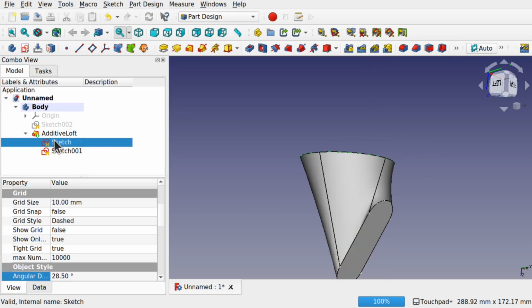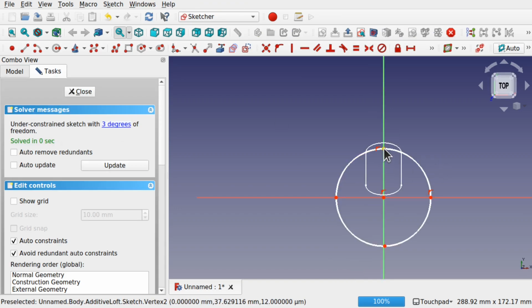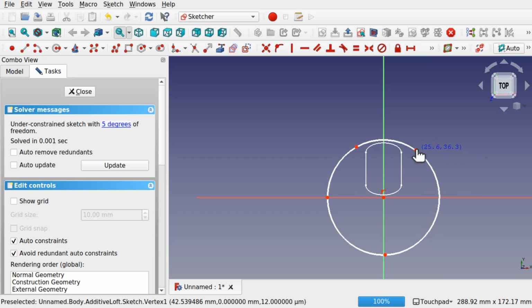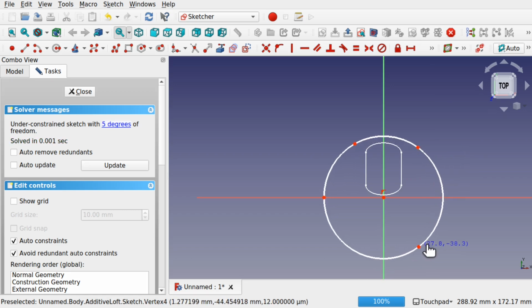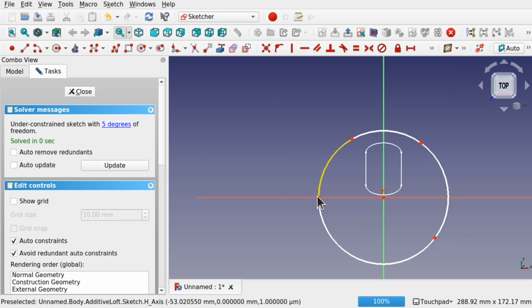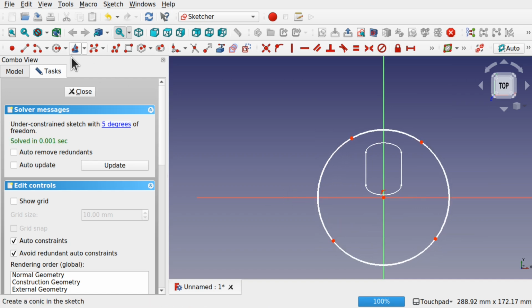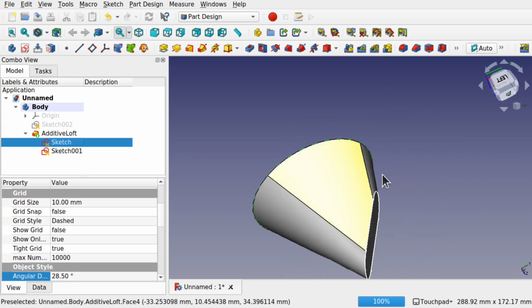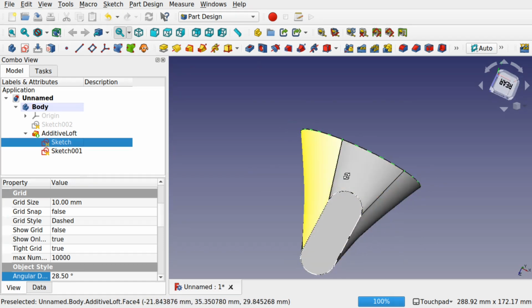let's come into our sketch and we can start looking. Let's get rid of that point on line constraint and looking at the sketch behind, which is the slot sketch, we can see that we need this point over here a bit. Let's get rid of this point on line constraint and this one up here and this one kind of over here and this one kind of this way. Hit close and then we've got better matching surface. There's no twisting of those vertices there.